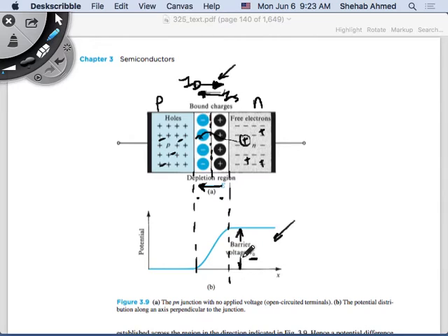So the capacitor is near the barrier, for example. Clear. What happens if I somehow add more voltage to this? If you add more voltage, you're making more holes diffuse to the electrons, or vice versa. Am I helping the diffusion current or the drift current? I'm helping the diffusion. So diffusion current will increase. Remember, this voltage was set up because of diffusion. You started diffusion, and then because of the diffusion process happening, you uncovered bound positive charges.